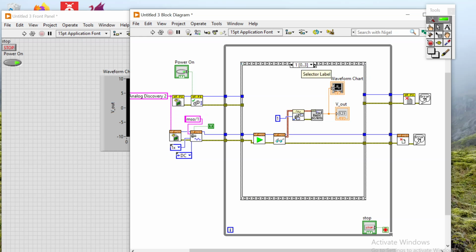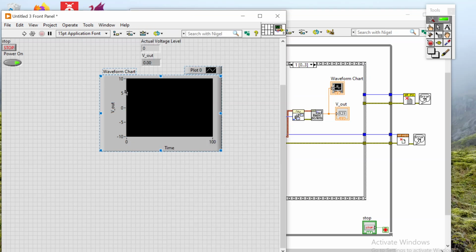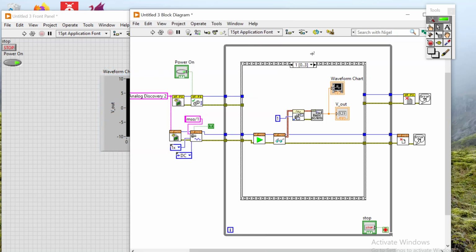And we'd want to run it now. I'm not going to run it because I don't have Analog Discovery at home with me, but you would run it now and you want to see, hey, does it make sense? Like, what am I expecting to see? Something between 0 and 5 volts, right? If I have 0, that means maybe I don't have power. If I have 5 volts, that means maybe there's something wrong with my circuit. It's not hooked up. I should have something kind of in between 0 and 5.